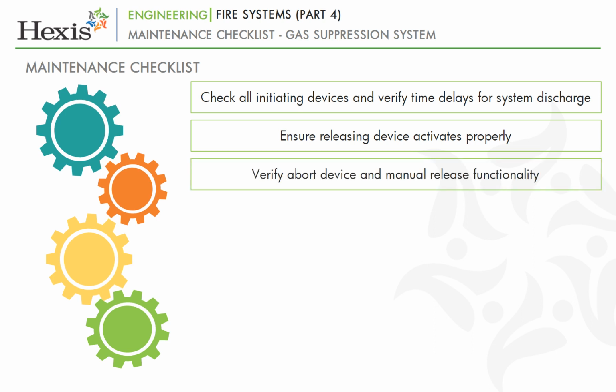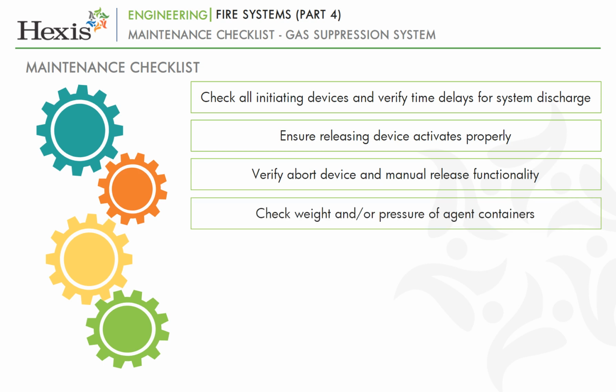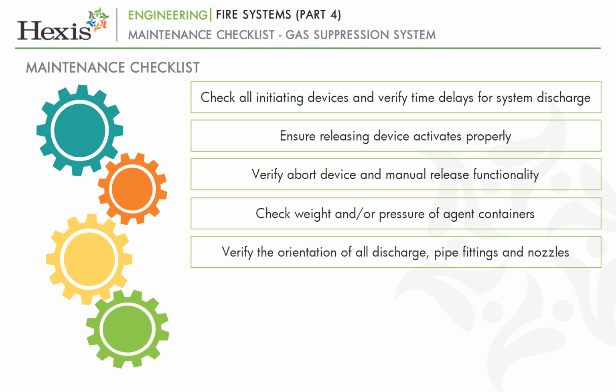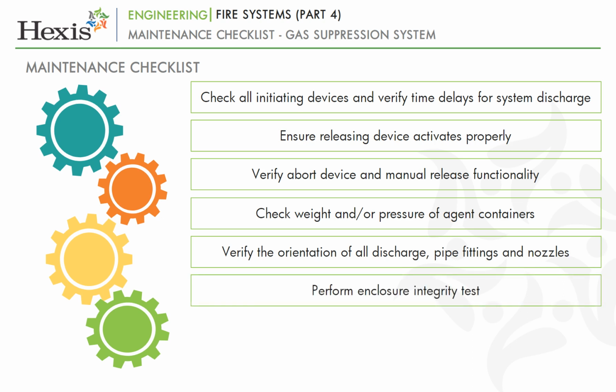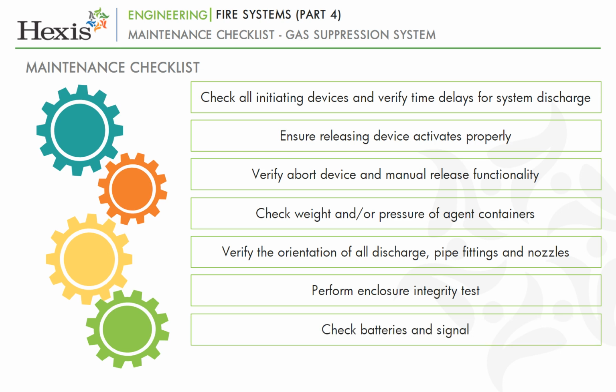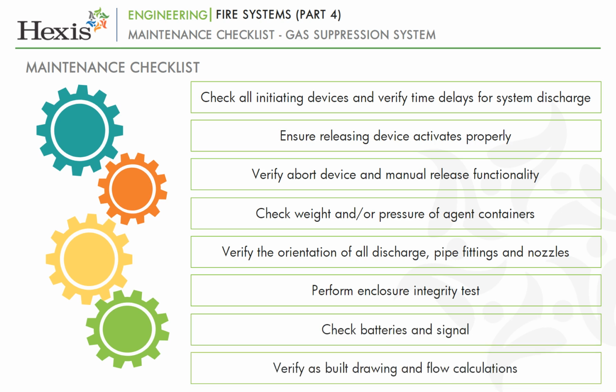Verify abort device and manual release functionality. Check weight and/or pressure of agent containers. Verify the orientation of all discharge pipe fittings and nozzles. Perform enclosure integrity test. Check batteries and signal. Verify as-built drawing and flow calculations.